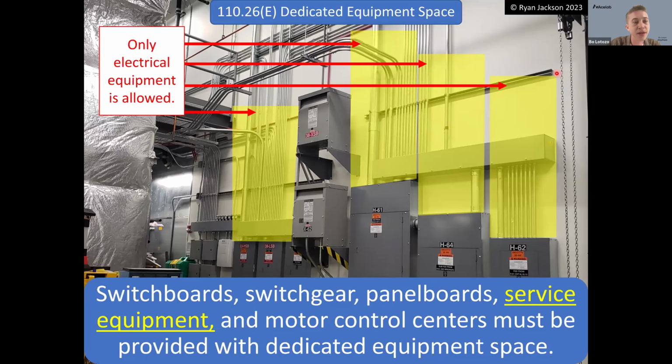All right. Does walking into another working space comply with exiting a working space? Great question. So yes, I think it does ultimately. If you have that big equipment, 1200 amp, 6-foot equipment, and you need to exit it on either side, if you walk into the working space of a different piece of equipment, then in my opinion, yes, you have satisfied that requirement.